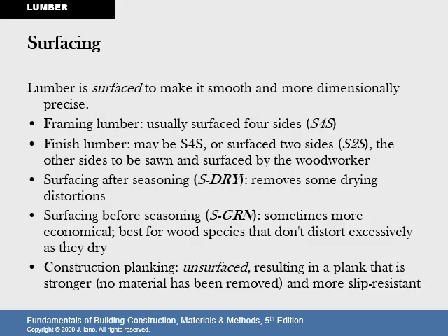Surfacing. Lumber is surfaced to make it smooth and more dimensionally precise. Framing lumber is usually surfaced on 4 sides. It's going to be seen on all 4 sides. Sometimes it'll be covered up, but you need to make it available. The finished lumber may be S4S, surfaced on 4 sides, or surfaced on 2 sides, which is S2S, with the other sides to be sawn and surfaced by the woodworker.